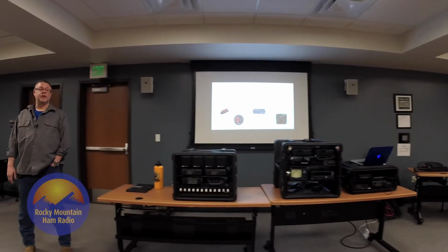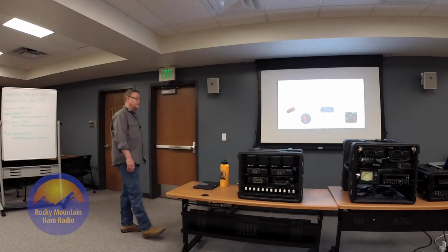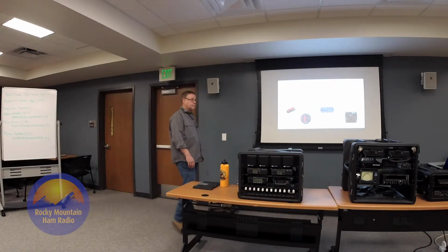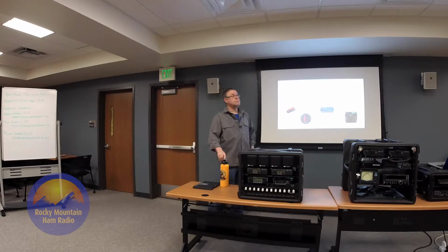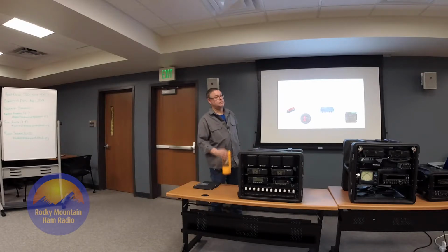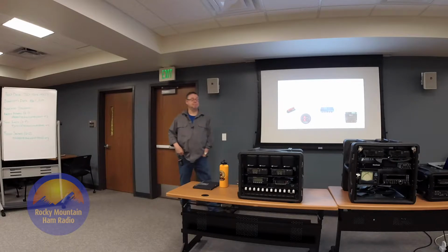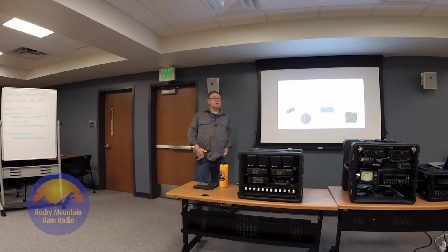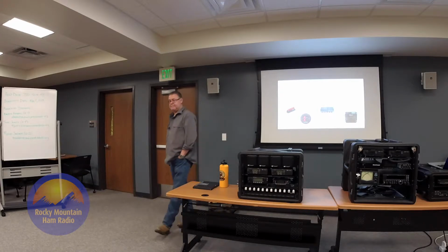Oh yeah, the rig runners, that is a handy feature, how they light up. The ones that we put in the trailer are the 80 amp, and they're double-sided. They've got 2 sets of 8, and every one of them has an LED behind the fuse. So when you pop it, the LED comes on, and that's really handy when you're stuffed in a closet or inside a little tiny box, so that you can see which one is gone.